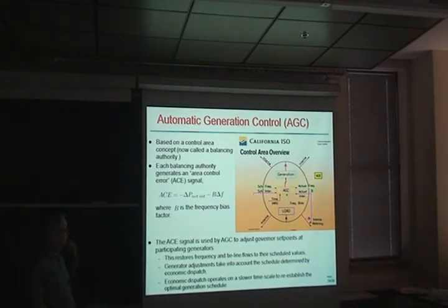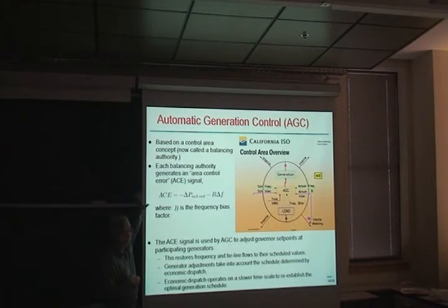So, to simplify things, there's another economic dispatch, an optimization that is saying, given the generation that is online at the moment, given the latest measurement of the load, what's the most economic way of rescheduling that? So automatic generation control takes the schedule from the economic dispatch, this optimization, and says, this generator is cheaper than this one, or it should be favored over this one, and distributes any change due to this in the most economic way across all of the available generation.